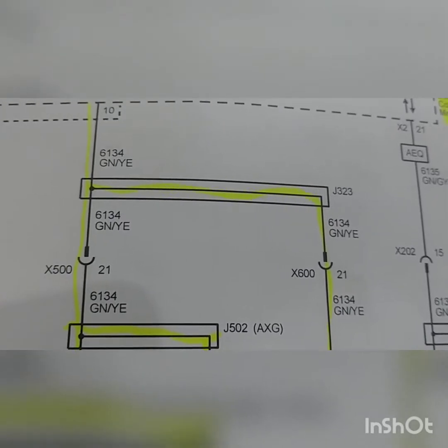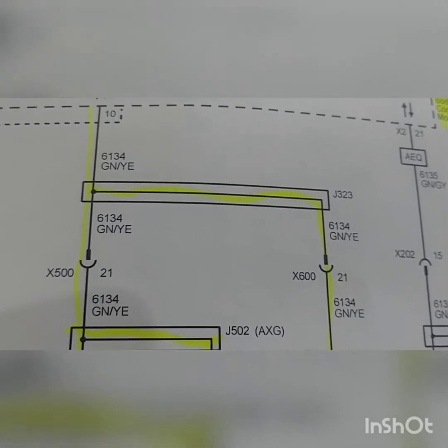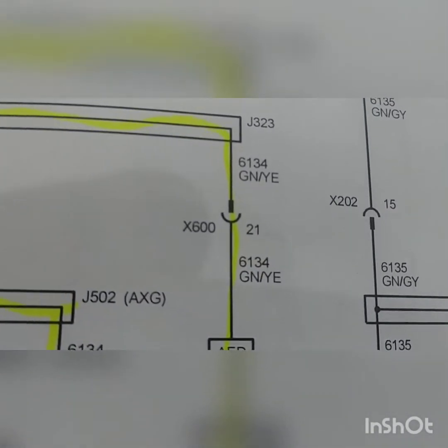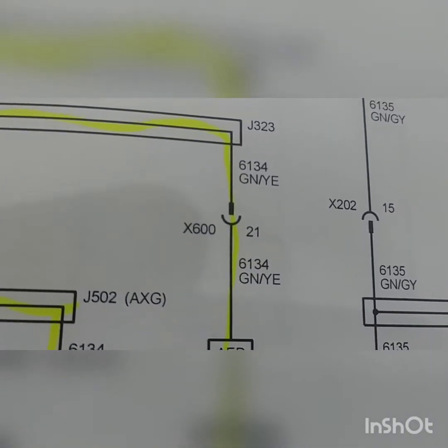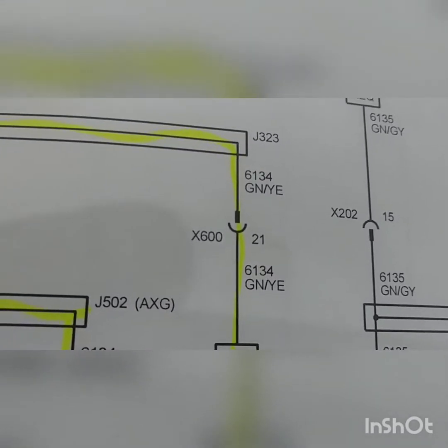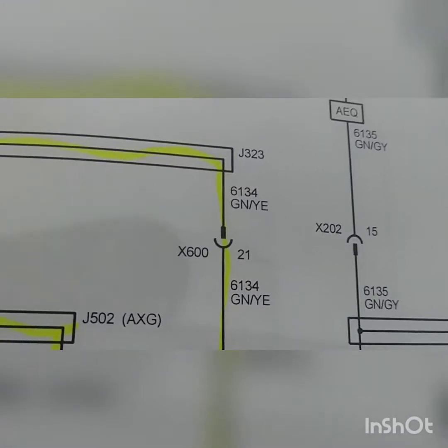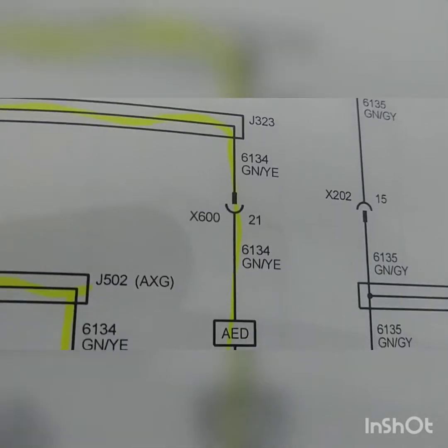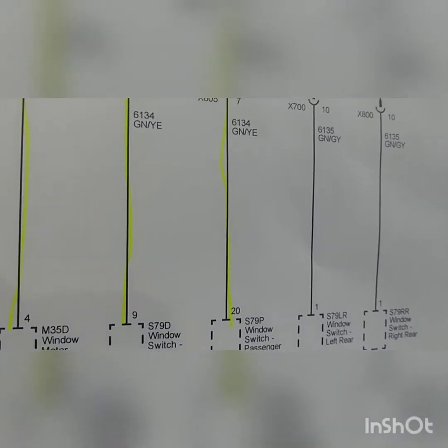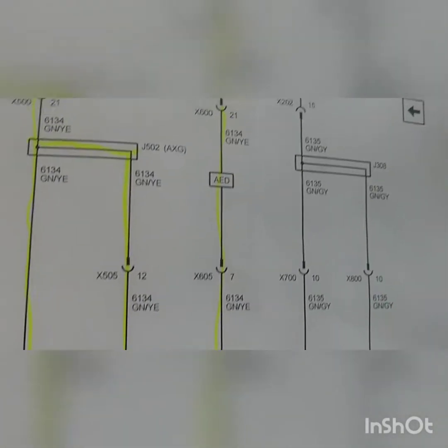but didn't want to take all that off, so I went to connector 600 and I tested out the circuit again. And now when I back probe pin 10 on connector K9, I had 12 volts again. So what's our problem? We only have 3 things left that it could be.